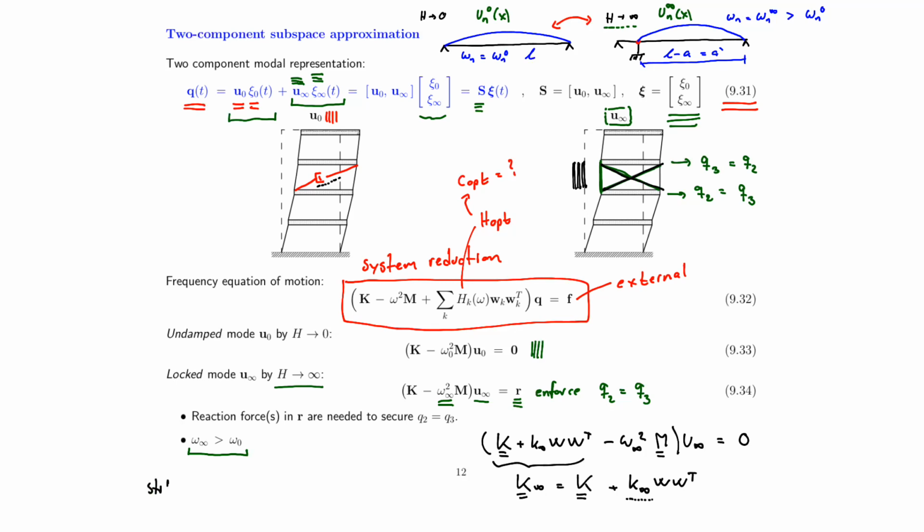So this stiff spring is typically chosen to be around 1000 times the largest diagonal element in the original stiffness matrix. By that, we will not get any numerical problems, and it's typically large enough to do the restrainment of the mode shape as shown in the figure to the right.